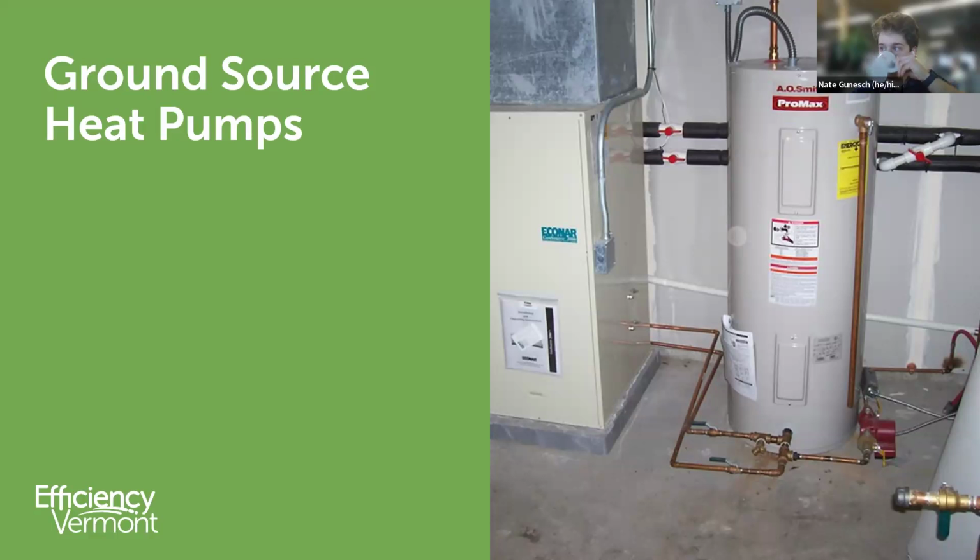Great. Okay, so Heather asks, is it possible to use an air to water heat pump or a heat pump hot water heater to preheat the water for an oil boiler? Yeah, that's a good question. I mean, an air to water heat pump can be tied into another hydronic system. They could probably serve the same tank. I think that's a little bit of a custom design, but you could absolutely work with a designer to do a system like that.